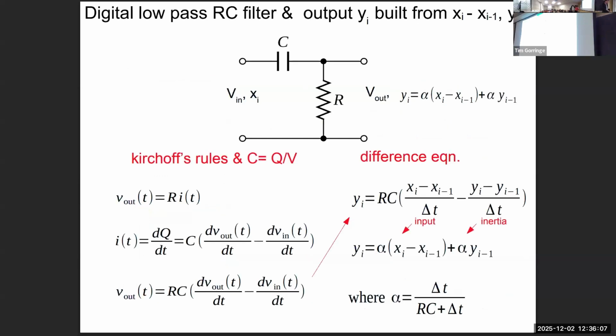We didn't do this for the high pass filter, but here is how an equivalent program will work for the high pass filter. For the high pass filter, the current value of the output is determined by the previous value of the output and the change in the input. So that's the difference there for the high pass filter.